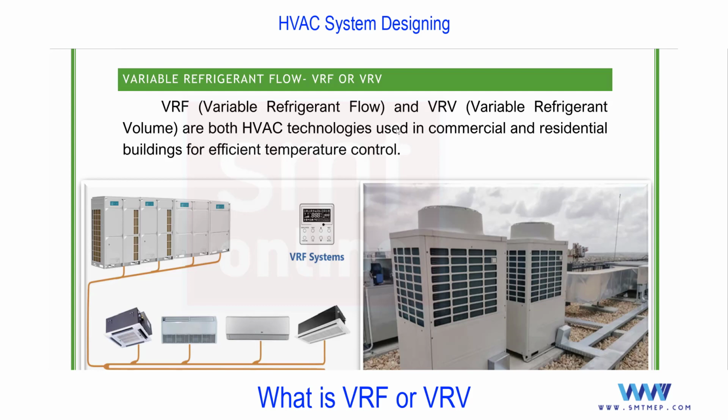What exactly is DX? I'll give you the idea after this topic. At this level, remember, DX system means the refrigerant is responsible to cool the air, compared with the chilled water system. So VRF also comes under DX system. And if you compare VRF with the split system, the major difference is that in a split AC or ducted split, you can connect one indoor to one outdoor. But in case of VRF or VRV, we have the option to connect multiple indoors to one outdoor.